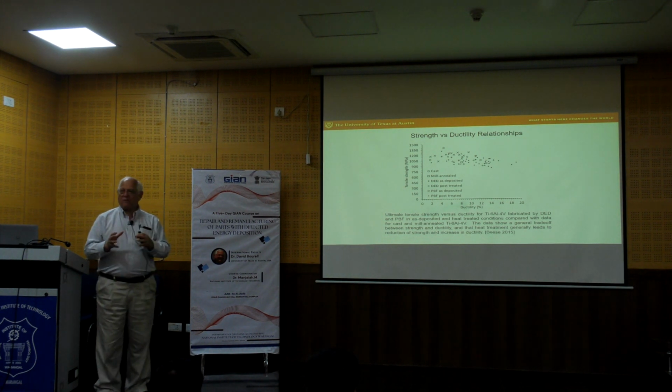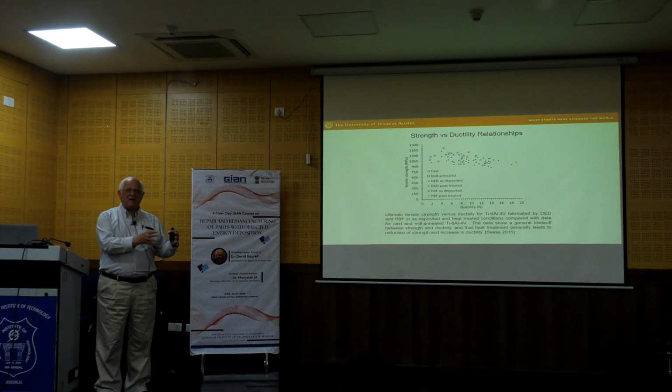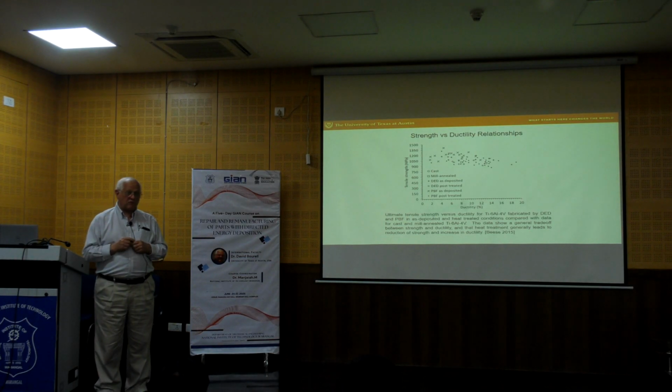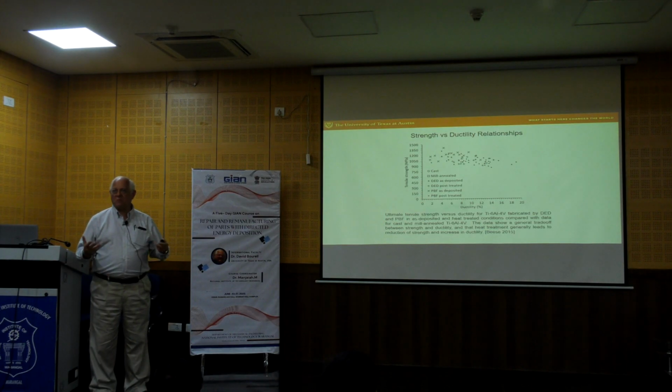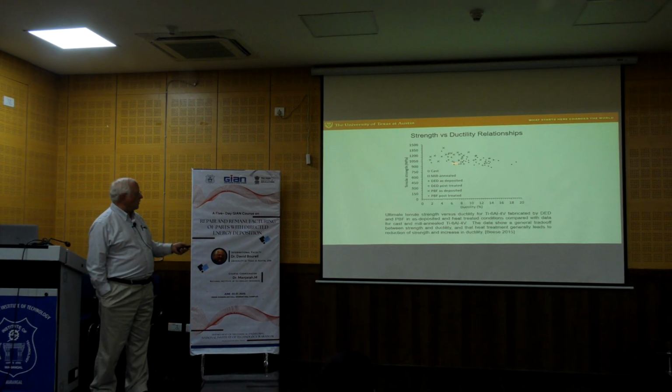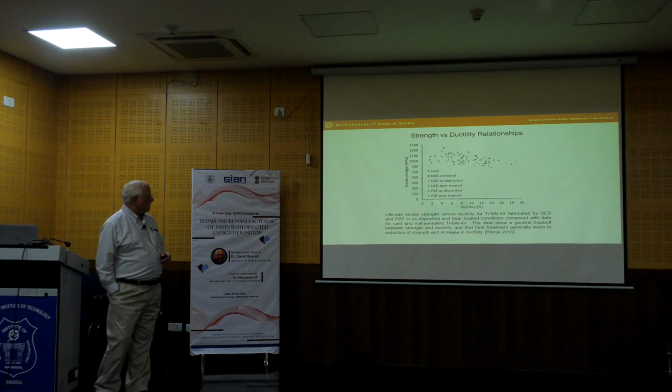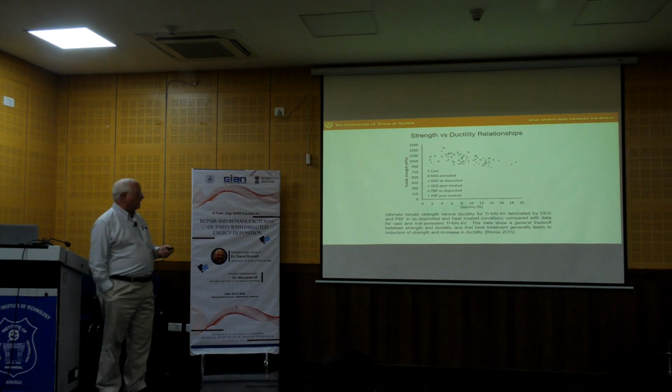Maybe one build has a higher density than another build, and from a strength perspective it really has no effect, so we see this relatively tight strength band, but the ductility is extremely sensitive, and so we get these very wide measures of ductility.